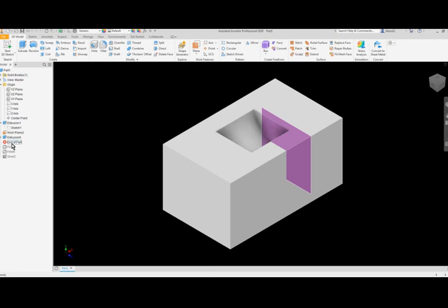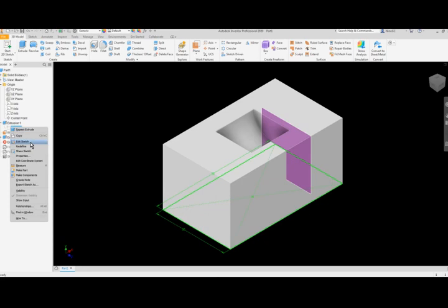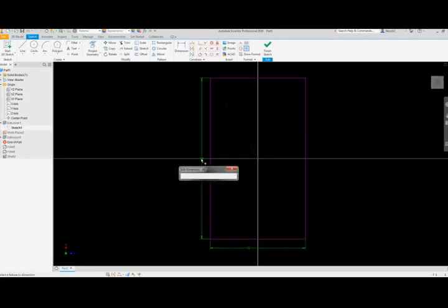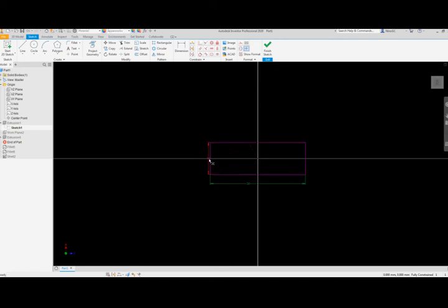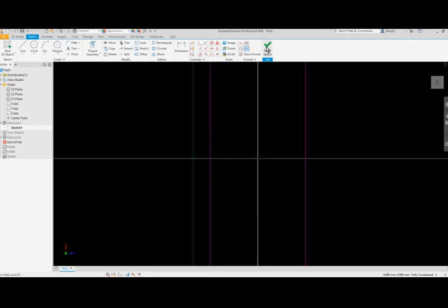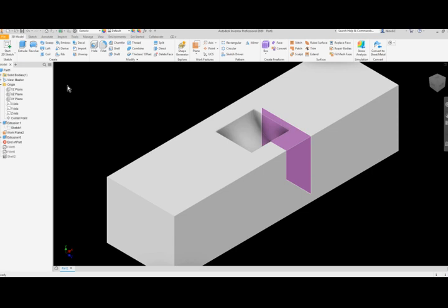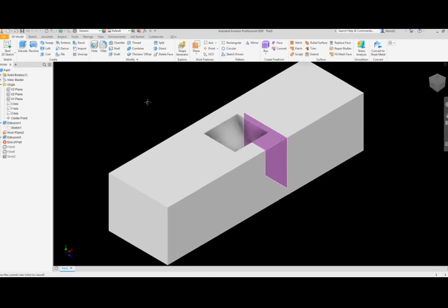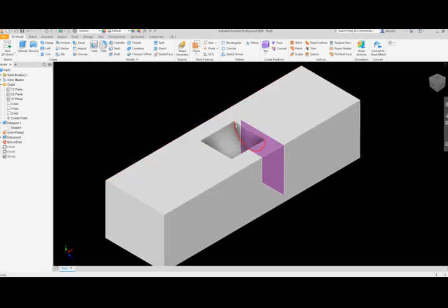What is the benefit of this? Well, if I were to increase the size of the sketch from its original of 50 to 100, and finish my sketch, that remains always central. So I do not have to worry about ensuring that I have a setup. I can do a similar operation, a little less effective, using sketched features.